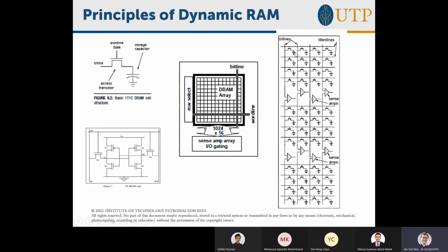Just now we told you that this capacitor is not held at 1.8 volts or 1.1 volts, and definitely not at 3.3 volts or 2.5 volts or any of those CMOS voltages. It's actually only a few tens up to 100 millivolts. So you're going to ask me, Dr. Ho, if it's only 100 millivolts and it reads out here, what do I actually read out? It's like 100 millivolts, that's like logic 0. So logic 1 is logic 0, logic 0 is logic 0. I don't get it, right? And you'd be right. And this is how it's actually done.